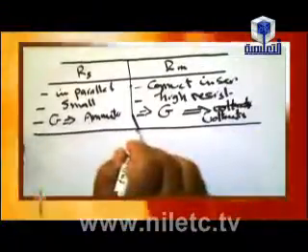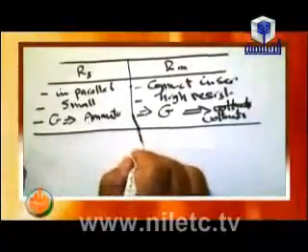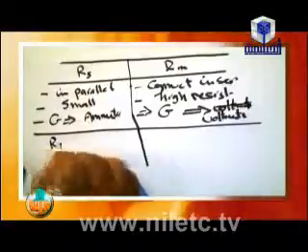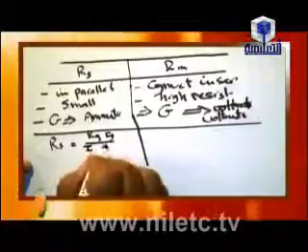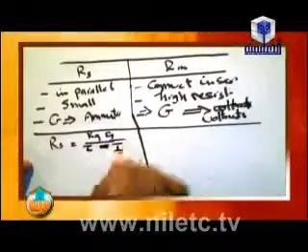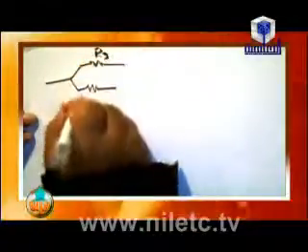So if the question is to deduce the law of shunt and deduce the law of multiplier: RS equals RG IG over I minus IG. We can deduce this law as follows. RG, RS, the current passing is IG in RG and IS in RS.